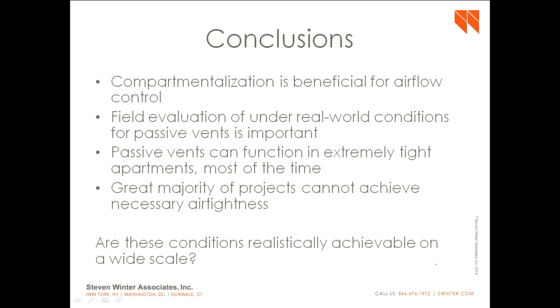So the conclusions that we draw from the air pressure monitoring that we did, and I think all of you will agree, is that compartmentalization is beneficial for the operation of the building overall. And if you've ever tried to specify or test a trickle vent, you realize that getting actual in-field performance of these is very important but difficult to do.